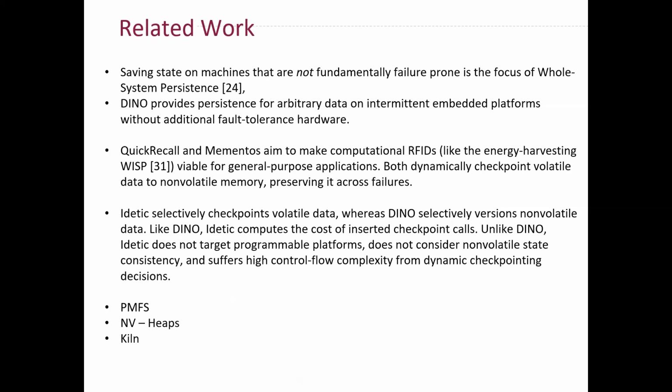Now, unlike DINO, neither of these systems addresses inconsistencies in non-volatile memory. Also, both Mementos and Quick Recall dynamically decide when to checkpoint heuristically at loop back edges and function returns. By contrast, DINO checkpoints at each programmer-defined task boundary, and so DINO has fewer failure recovery targets.